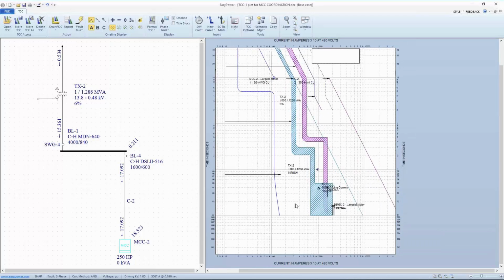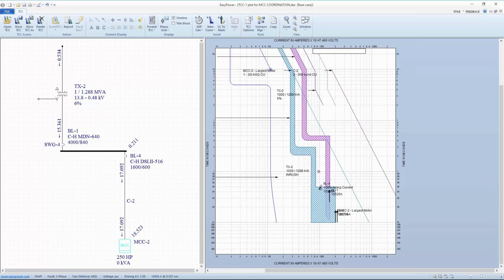And again, the question that can be answered here is, where does the time frame come from? It comes from exactly where this little trap or triangle crosses the upper boundary. If you look down here at the bottom of the screen, you'll see the points on my cursor setting. And so we'd expect to see right at 50 milliseconds an arcing fault would clear this breaker. And so that's what would be utilized to calculate my incident energy.